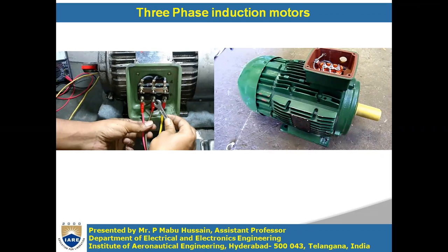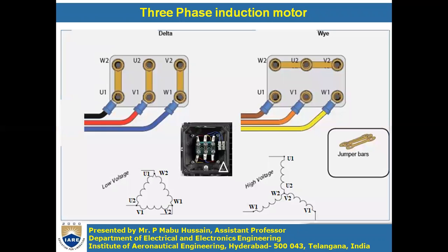If the three-phase induction motor has all 6 terminals outside, then only can you go for the star delta starter.